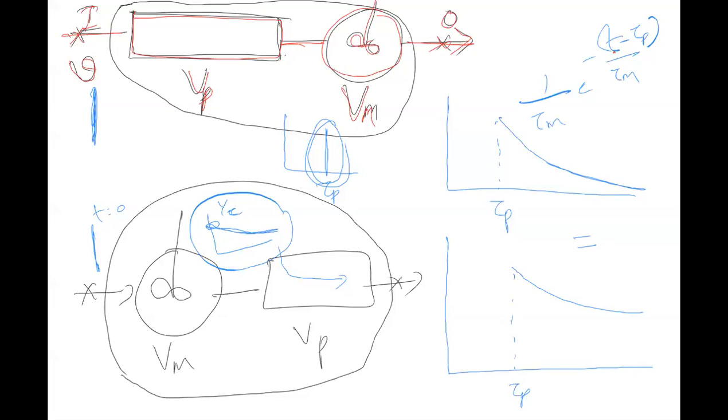But you will ask, PFR followed by CSTR is good for second order, no? Greater than 1. Here I got the same RTDs because these are non-reactive fluids.